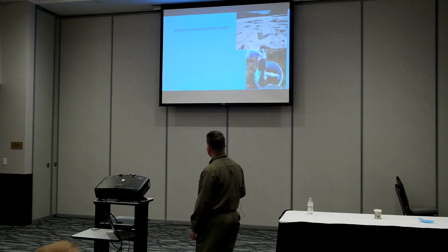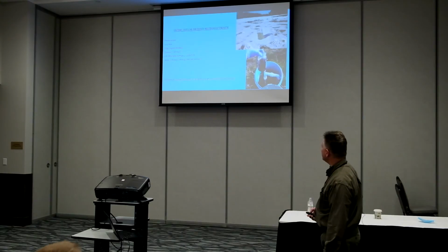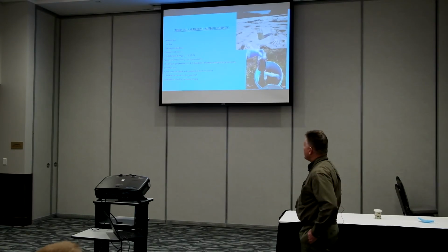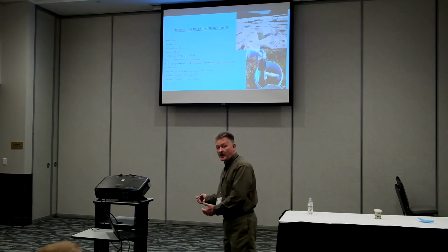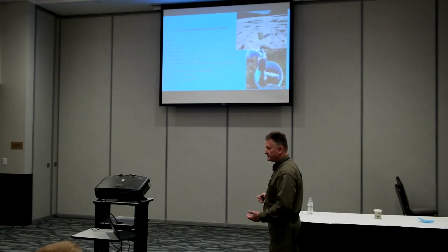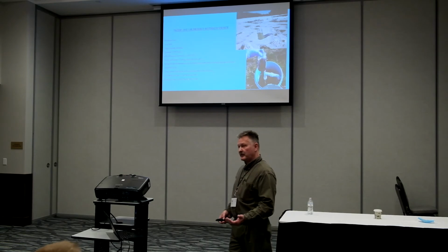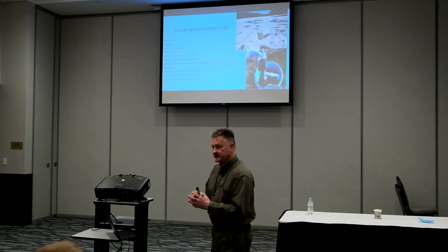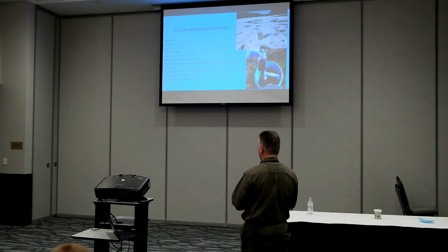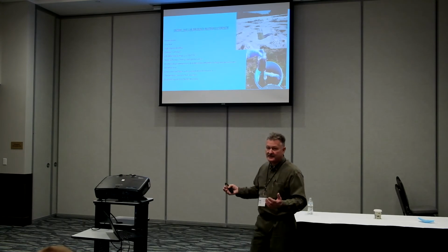So, factors that influence the wastewater strength. I'm going to click through these. Excess use: if the system is receiving more wastewater than it was originally designed for, that's obviously going to increase the waste flow. Low flow fixtures have a tendency to concentrate our constituents and can create high level wastewater. High organic loading, for instance, from a restaurant and so forth.